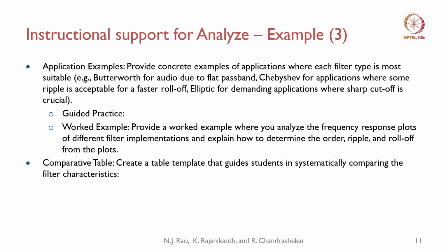Then we also look at application examples, providing concrete examples of applications where each filter type is most suitable. For example, Butterworth for audio due to its flat pass band, Chebyshev for applications where some ripple is acceptable for faster roll-off, and elliptic for demanding applications where a sharper cutoff is crucial.